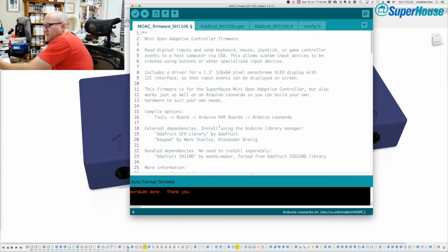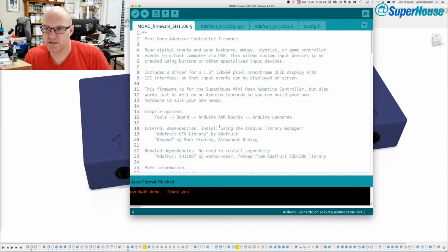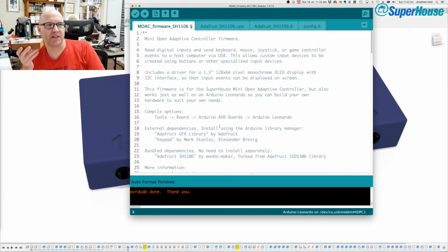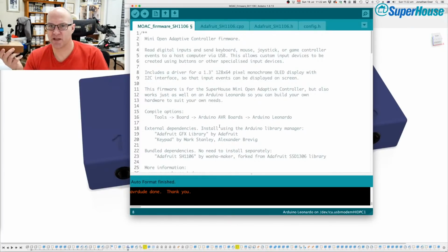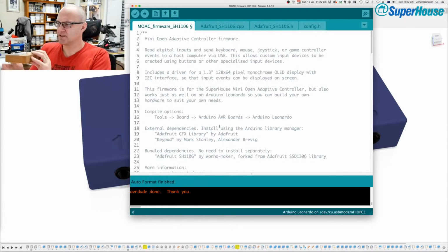So at the moment, our problem with this is not sensitivity. We've got more sensitivity than we need. I'm currently using 300 gram rated load cells. So they are rated to a maximum of 300 grams full scale, and beyond that you can damage them.